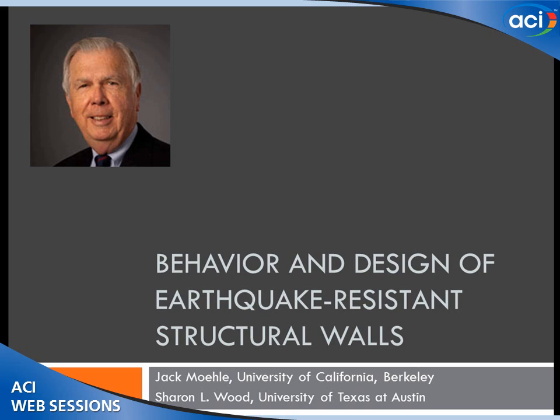But today I want to talk about one aspect of Gene's work that was really influential for earthquake-resistant structures, the subject of structural walls. And by the way, we are going to stick with the term structural walls in this presentation. One of Gene's insistences was that they be called structural walls and not shear walls, because they are intended to respond not through large deformations in shear, but to respond as structural elements, maybe mainly in flexure.